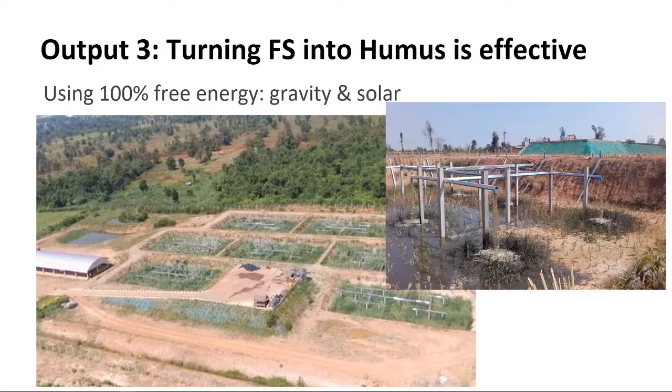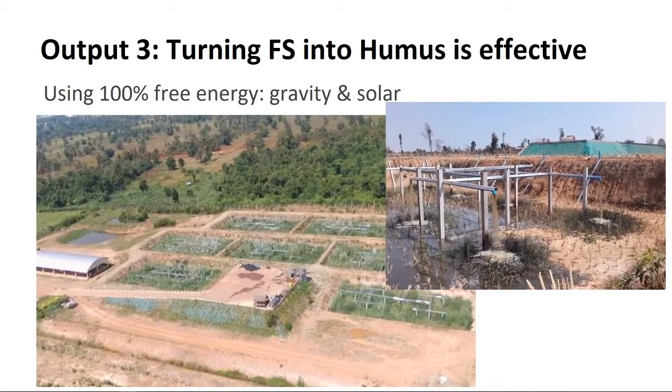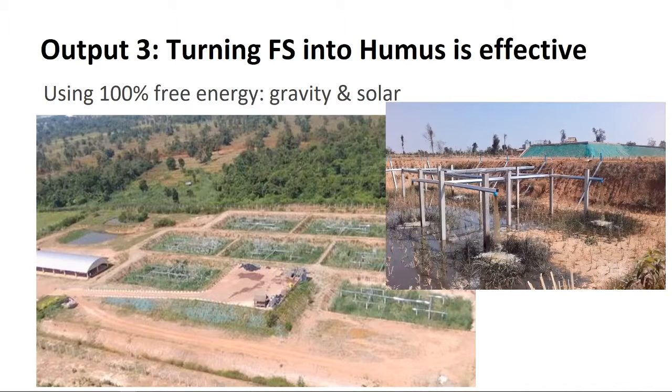So let me explain it to you in 2-3 words. The trucks come here onto this ramp, and they discharge their sludge into this flushing tank. The flushing tank is higher than the planted drying beds. It means that with this flushing tank, we can flush, and we can have a quite good hydraulic distribution in all the beds. And you can see on the pictures, on the video, how it looks when we flush from the flushing tank. This picture was just the hydraulic test we did 2 years ago, just after the construction.